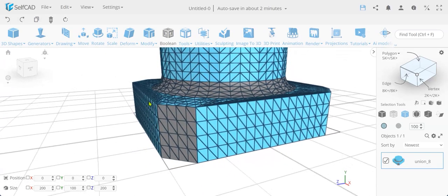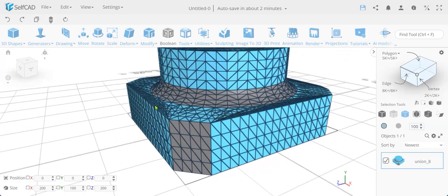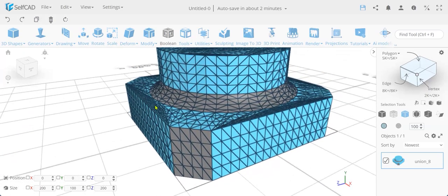It's important to remember that offset mode hasn't been replaced. In fact, it remains the fastest and most efficient option for models with clean, quad-based topology. For simple geometry, offset mode produces excellent results while keeping the mesh lightweight. Solid mode is designed for those situations where complex topology would otherwise lead to stretched polygons, self-intersections, holes, or distorted bevels. Having both options gives you the flexibility to choose the workflow that best matches your model. Use offset mode for speed and clean topology. Use solid mode whenever you need the highest quality results on complex geometry. Together, they provide the best of both worlds.